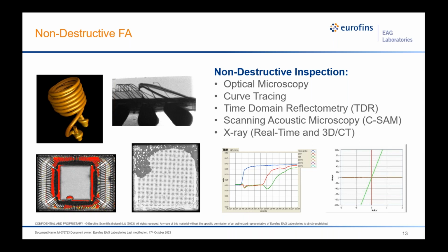The two plots on the bottom right are more electrical plots. The one that says TDR, which is second from the right, is a technique that we use for detecting discontinuity in transmissions or in trace paths. The idea is that when you send a transmission down a trace path and it hits a high impedance, part of that transmission is reflected.